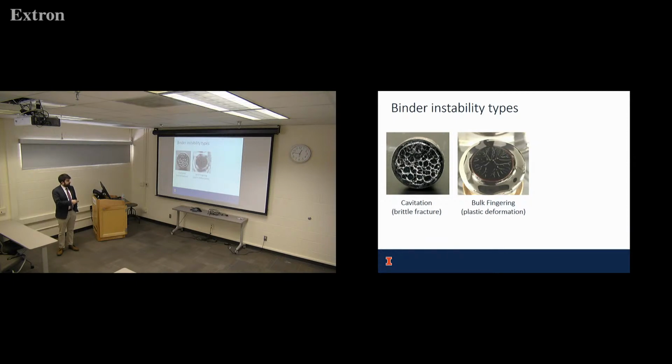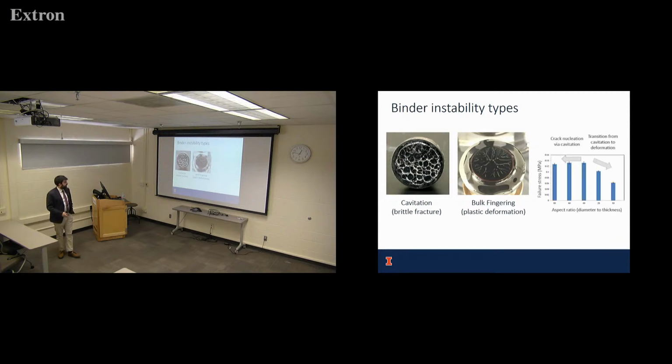Actually, this test was run in DSR because that's where we could create a thick film and load it slowly. That DMA capability was okay. So this was from DSR. This is from our DMA. And what we notice is when we start to raise that aspect ratio higher, which means thinner film, the strength of the binder gets pretty uniform and it's higher.